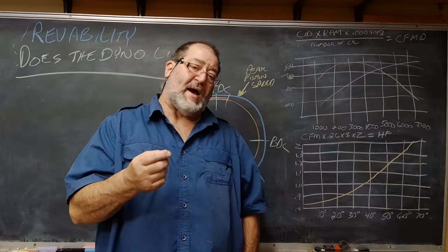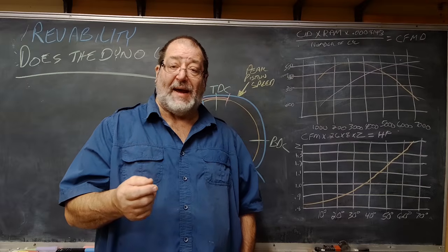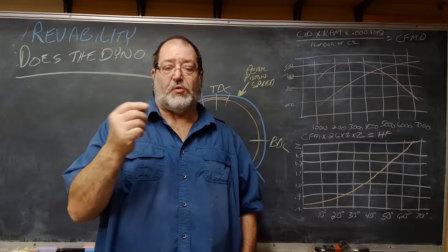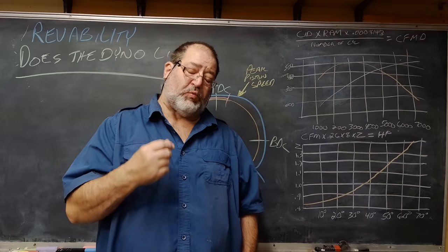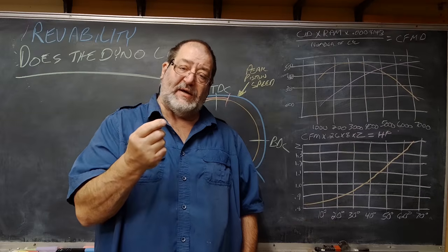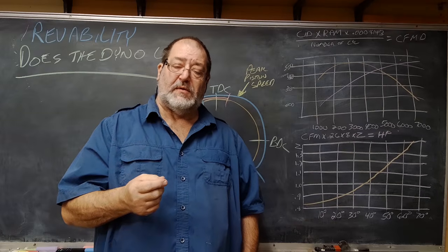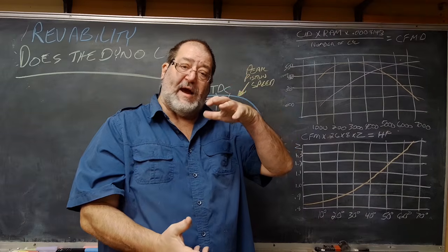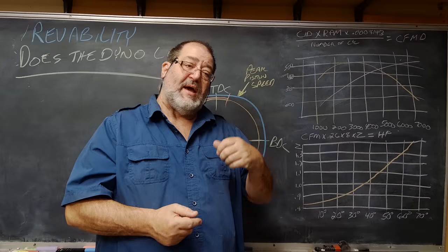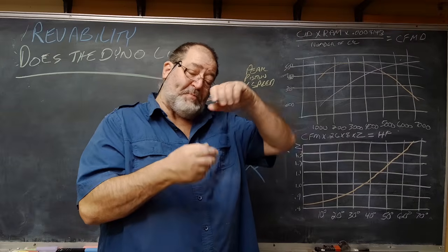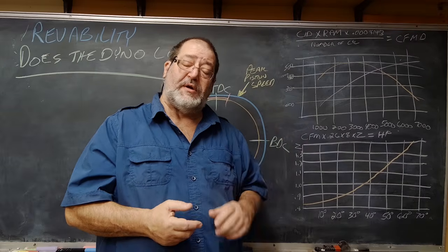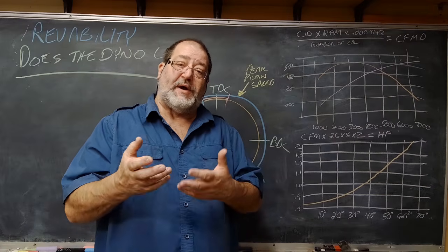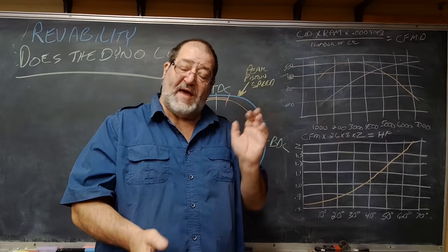But at the moment, we're not even really talking about power band. I'm just talking about the ability of the engine to rev. And what that is really, is how easy it is for that engine to breathe, because you have to draw in the air. You're creating a vacuum. If you're creating a much bigger vacuum than you should, then you are using up work in the engine to draw in that air.